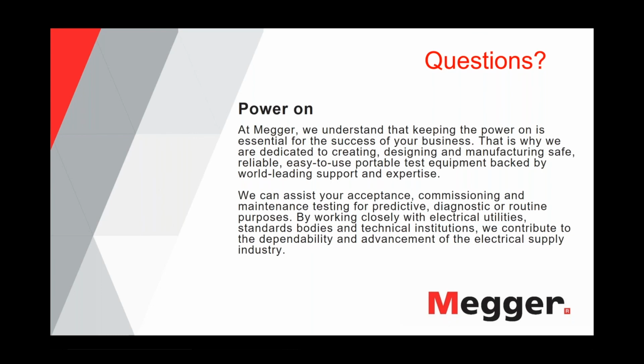In the IEEE standard, it talks about mineral-filled EPR. Is there a way to know if your EPR cable is or is not filled with mineral or mineral-filled? Well, that is really the difference between XLPE and EPR cable. EPR is a copolymer, but it's also filled always with mineral fillers. And so there is no EPR cable without mineral fillers. So any EPR cable has mineral fillers.